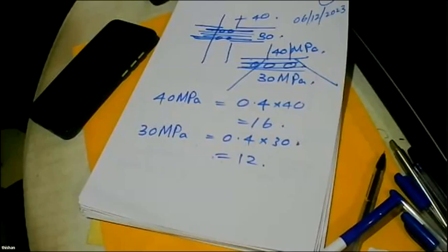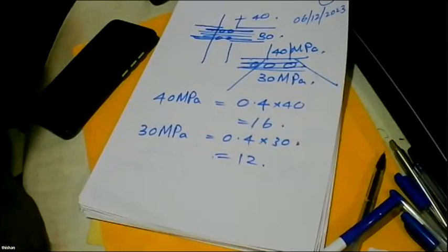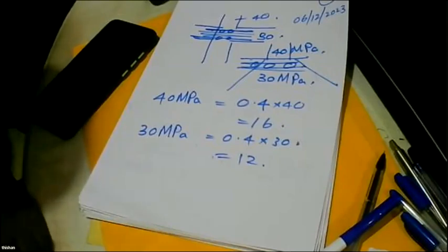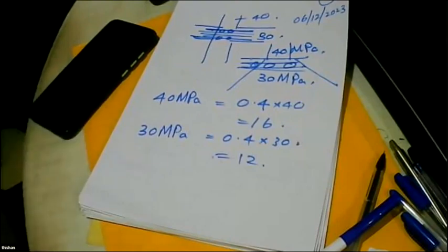You can do pile rafts only in areas having very good laterite soil, where the bedrock is deep, where you are going to stop the piles in the laterite soil as friction piles. Then you can go for a pile raft. But otherwise, if you have end bearing piles, going for a pile raft is wrong.